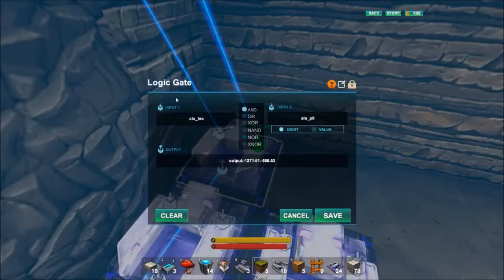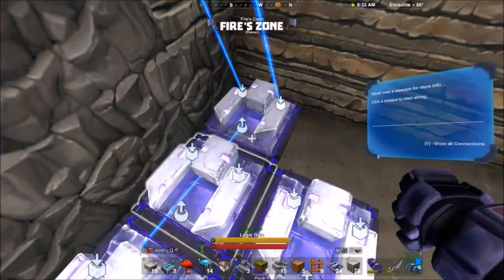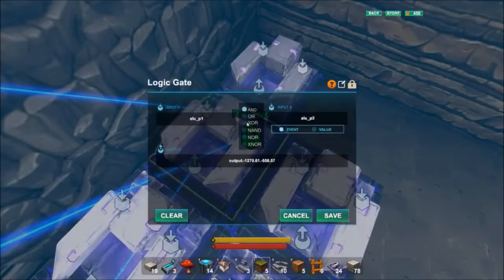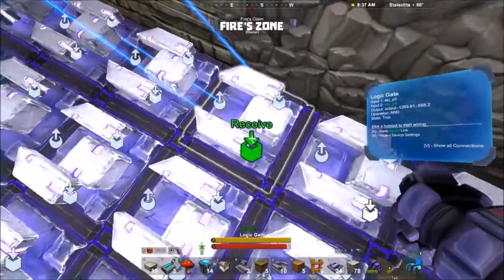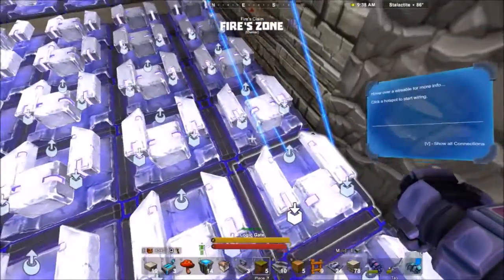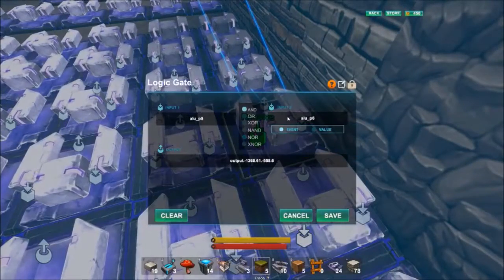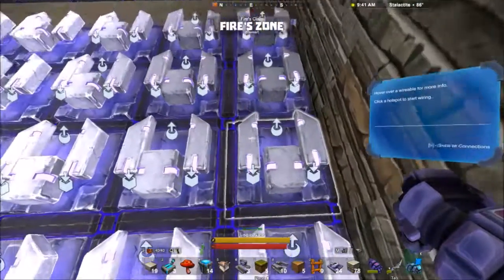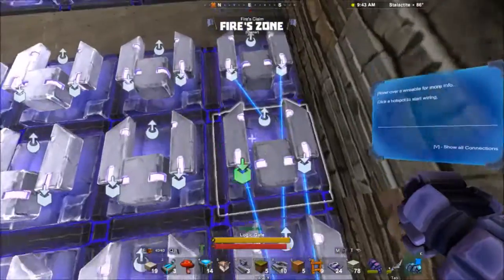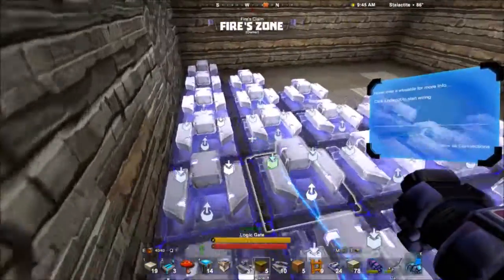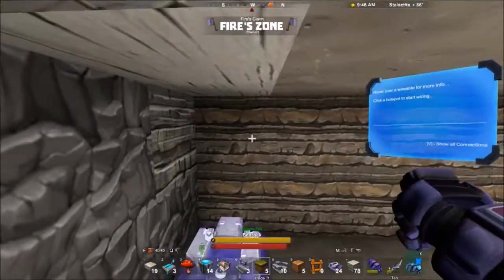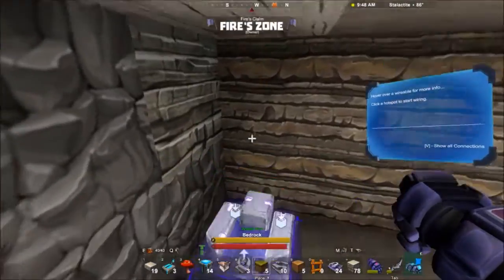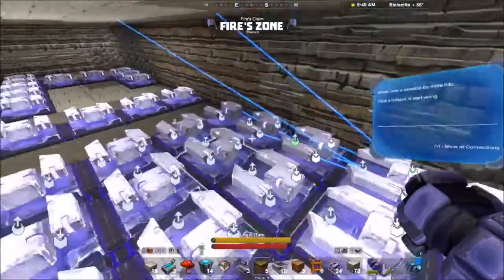So this one is when the increment, but we're on bit 7, so it has to be propagated by 0, it has to be propagated by 1, by 2, by 3, by 4, by 5, and by 6. All these are just to get the logic all the way through. But basically, it gets generated by the increment and it's propagated through the whole ALU.